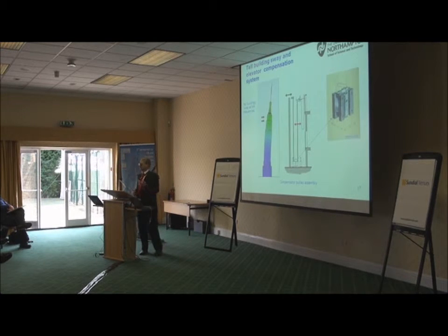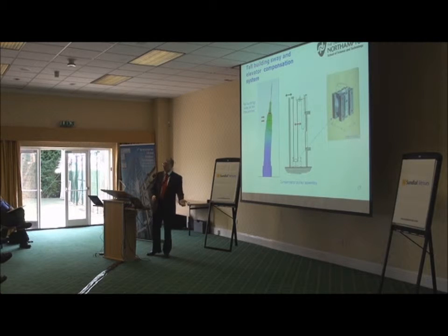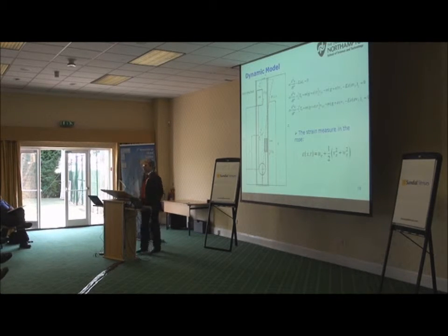What you will see vibrating is typically the compensating ropes, which, as you know, in tall buildings have to balance the masses of the hoist ropes. And the compensating rope, here's a counterweight, here's a car, a set of ropes, tensioned by the weight, the compensating pulley assembly.